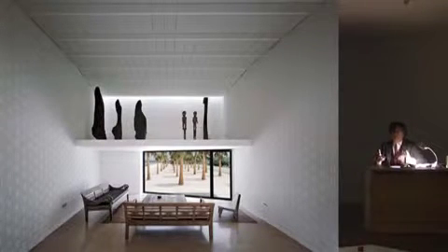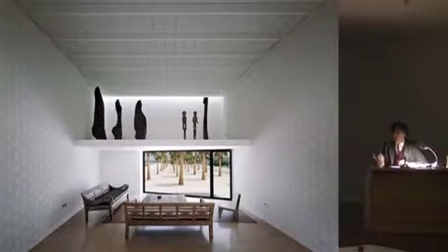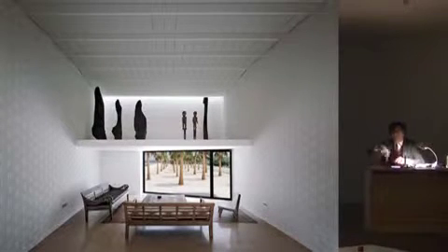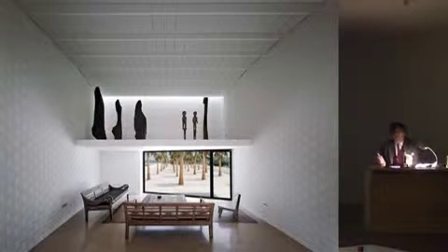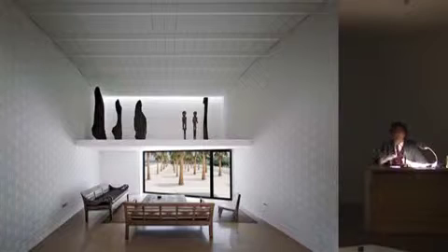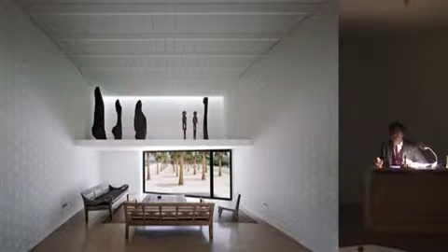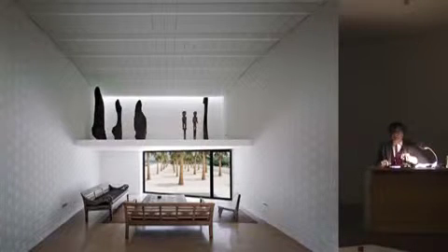But if you want it to look smooth, like smooth floor covering, and you know, people are supposed to live there, and in the kitchen there might be liquids being poured, so you crystallize. You use the terrazzo polishing machine. You do, I don't know, 3, 4 stones and you polish, and it's fantastic terrazzo. If you want it a little bit more coarse, more porous, more absorbent, then you give it one less stone.